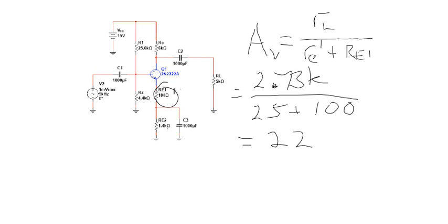Another problem that we can run into is what happens if this resistance gets small. Remember, that resistance feeds into the gain formula. It goes in parallel with the collector resistor to make that little RL. So if this number is small, that's going to drive our gain way down. So I'll show you one more trick that we can play to get that resistance up, so to speak.